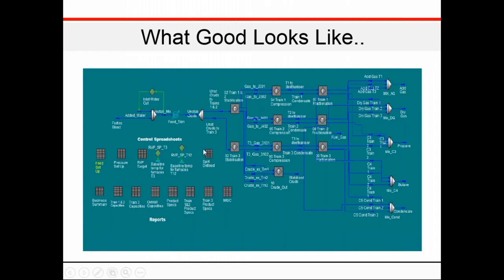Anyway. All right, so this is what the whole stream looks like. I know it's looking a bit busy, but this is a beautiful illustration of what a simulation looks like. You can see here we named the stream 40 blend. These thick blue arrows represent streams that have already been solved in HYSYS.